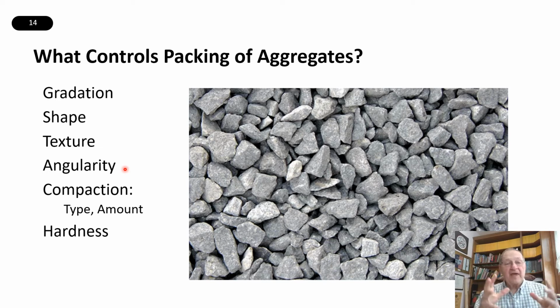Of course, the shape, texture, and angularity will influence how tightly together the aggregate particles will pack. So I have some flexibility there, but I have constraints because I have to meet this fine aggregate angularity requirement. Same thing happens if I have gravel, which doesn't have so many crushed faces, perhaps, and crushed stone.